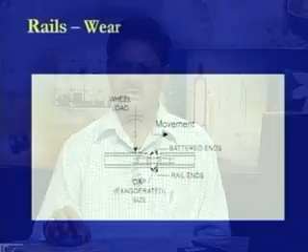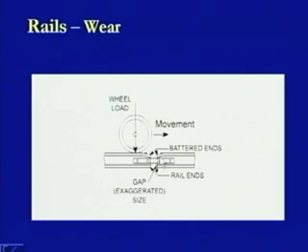Now, this is the case where the rail end is being shown, and as we have discussed, whether the two rail sections are at a different level or there is a movement of this wheel in this direction, what we found is that if this gap is either more or the rail sections are at a different level, there is hogging taking place. That is, this end of the rail section has gone down, and this is also termed as the battered end of the rail section. So, this is also a battered end of the rail section, and this is also a battered end of the rail section, whereas at the bottom it remains at the same level. So, this is one type of condition which got created.